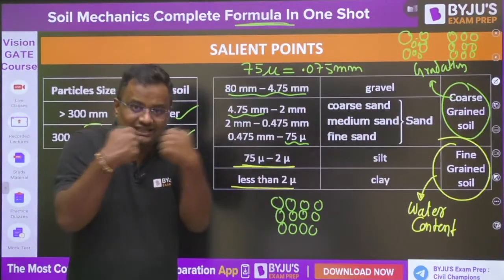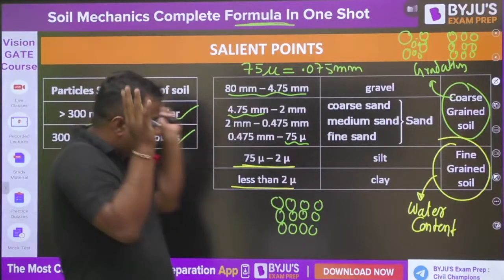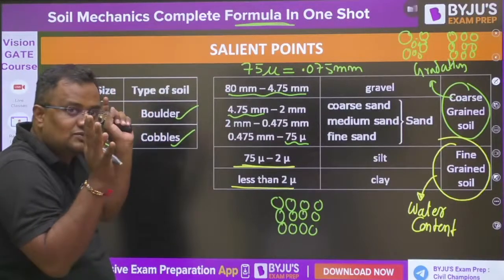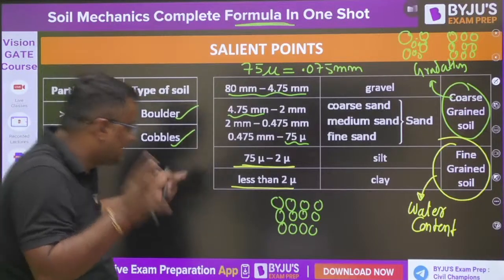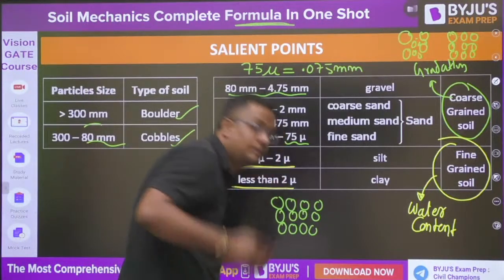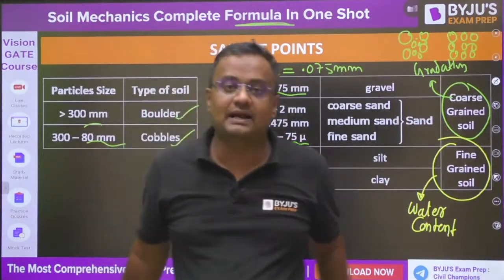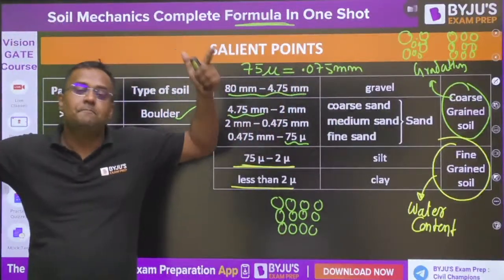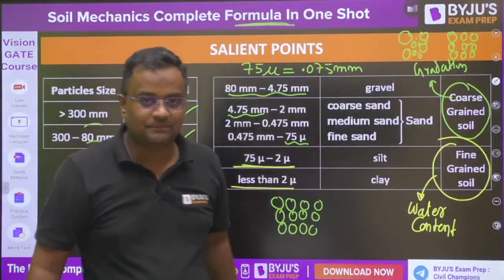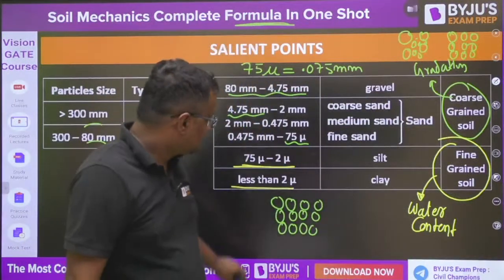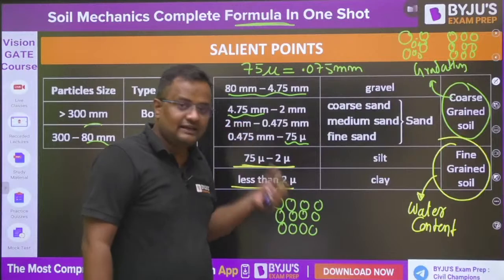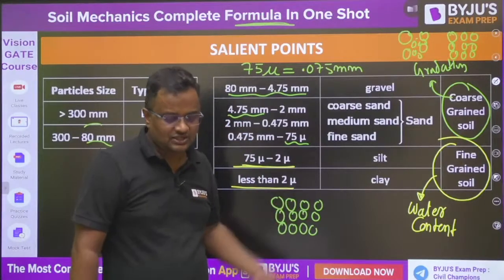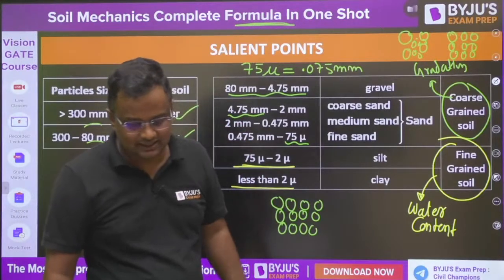Cohesion means there is still bonding. So from far you feel, this is a useless soil, small particles are not there to fit in the voids, but actually if you see from a microscope, there is attraction between the particles, that is cohesion. It is like from far you saw bald men playing, but going close you saw eggs boiling. Okay, so fine grain soil has a flaky structure and charge distribution is there.